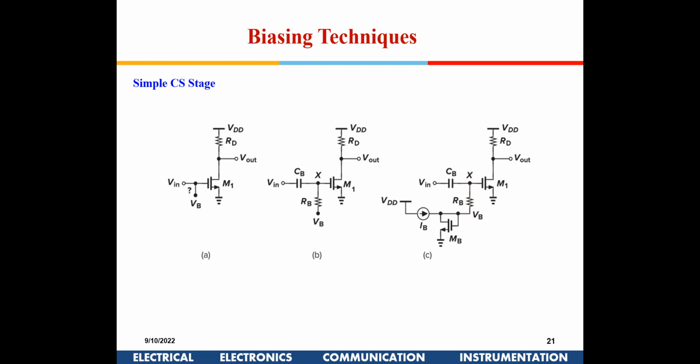Usually DC signals will be stable, right? No, it depends on where that signal is coming from. If you have an inbuilt DC which is stable, then it is okay, you can do that. Consider an example where we are generating VIN from a current mirror, some kind of reference voltage, or from the band gap output. These are stable outputs, so you don't require it. You can do that. I was wondering, because in the majority of circuits DC should be stable, but still we are using this kind of circuit.